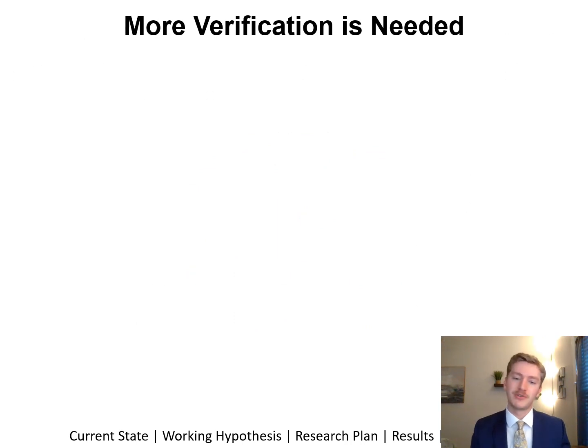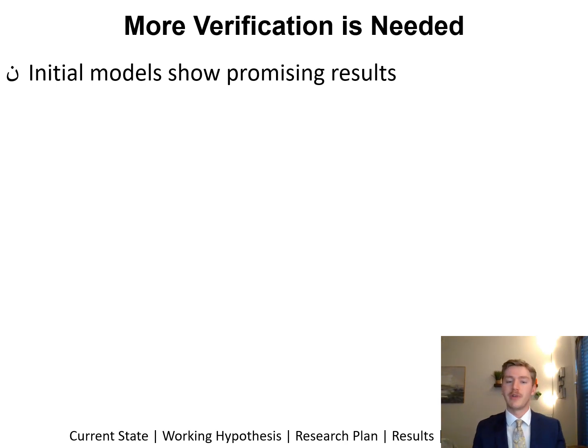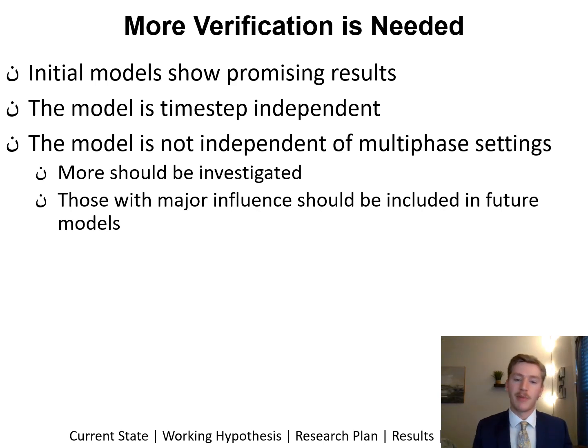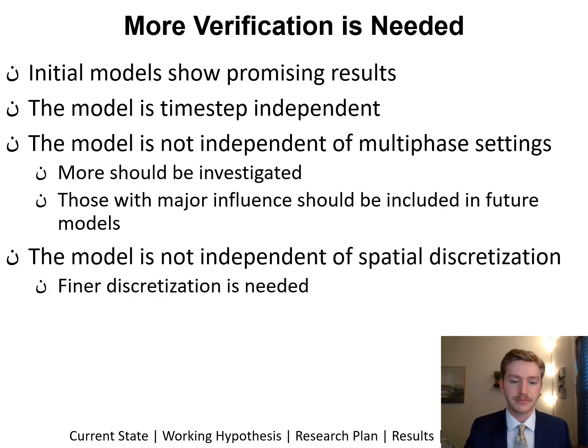What we learned from this study so far is that more verification is needed. The initial model showed very promising results, as there was an increase in velocity at the outlet, and there was quite a bit of vaporization within the chamber. We did find that the model was time-step independent. However, the model is not independent of multiphase settings, so more should be investigated, and those with a major influence on the results should be included in future models.